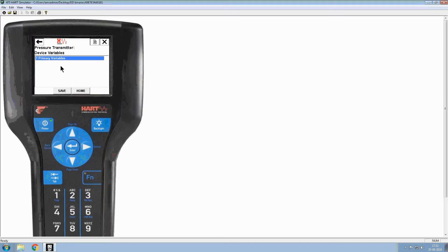The device variables provide transmitter output, range values, PV status, device identification and device revisions. This is a read-only section meant to give an overview of the process and the device. An exception is the shortcut provided to perform the essential procedures including zero trim and loop test.